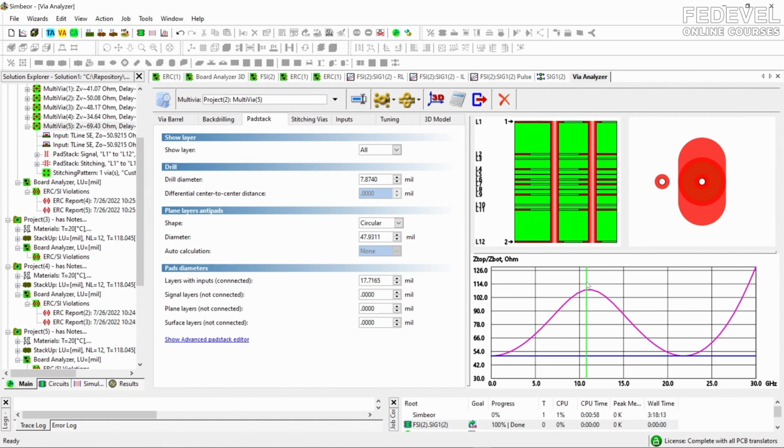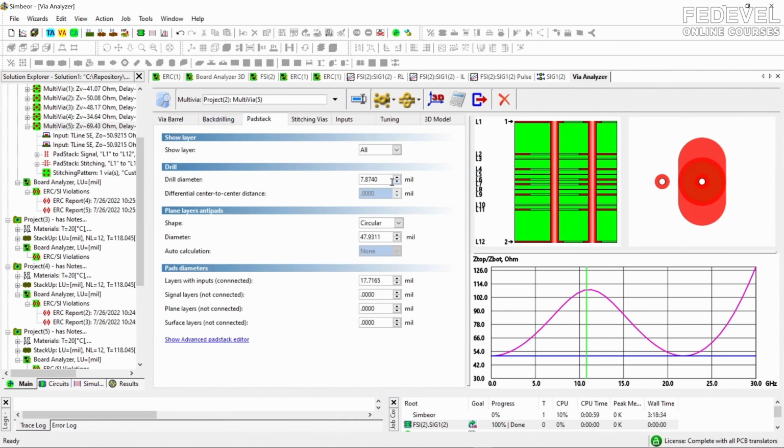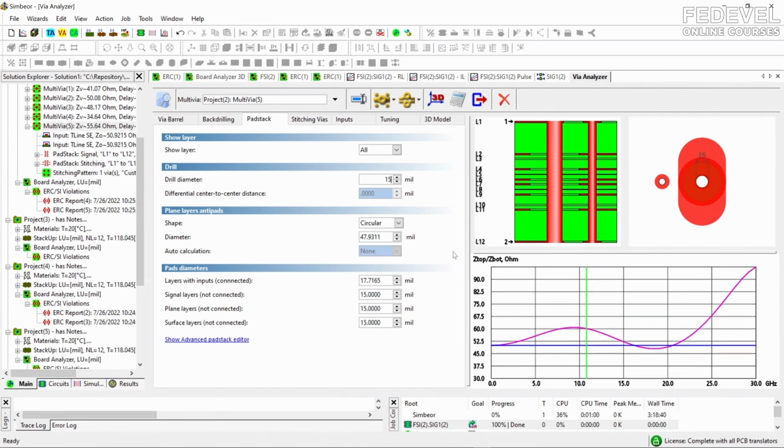The via impedance goes up here, as we saw with this red dot. So what do we do? And the bandwidth is sufficient for 10 gigabit per second, so 10 gigahertz here, green line. So what do we do? In this case, we can increase via diameter, like use wider, and that basically reduces it. Wow. Exactly, and maybe reduce a little bit the antipads to have more capacitance.